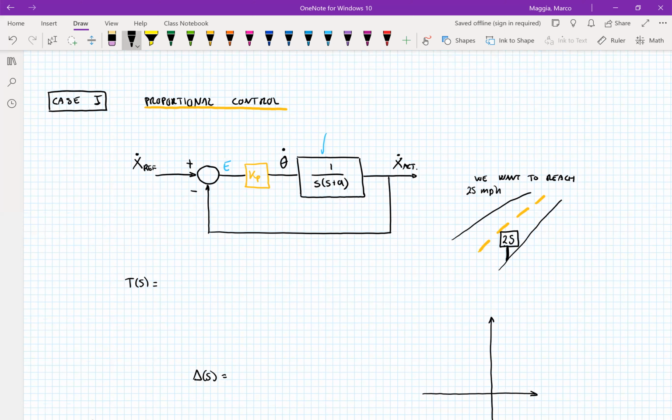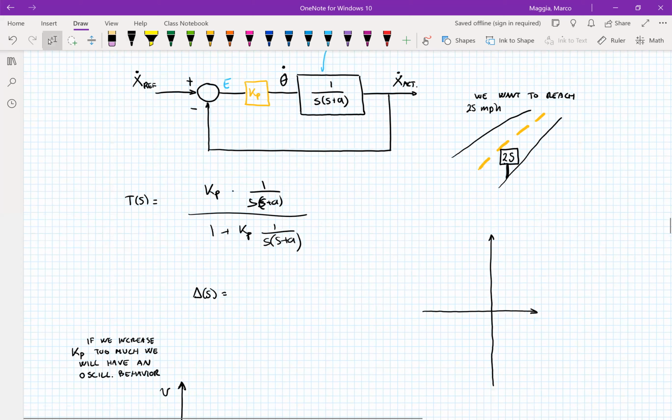All right, so let's take a look at the closed loop transfer function very quickly. Here, there's nothing new, so I'm going to go a little bit fast. All right, so now we have the freedom of choosing a parameter, Kp. So you see here, we're dealing with the perfect example that we've studied, that is the root locus. We have one parameter that we can vary. So very quickly, we can draw the root locus for the system.